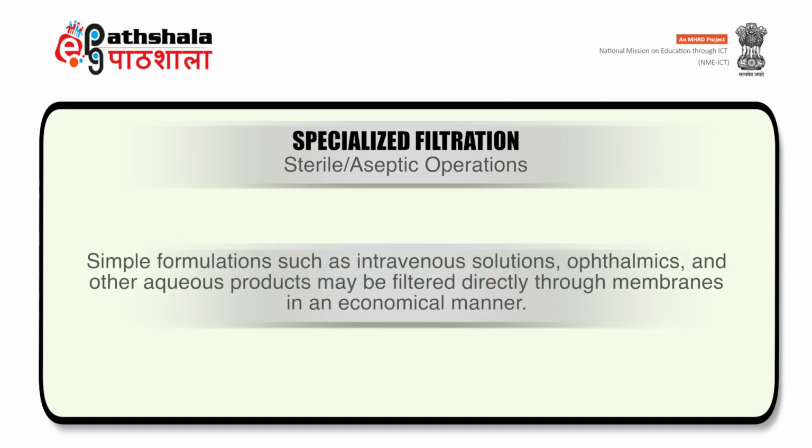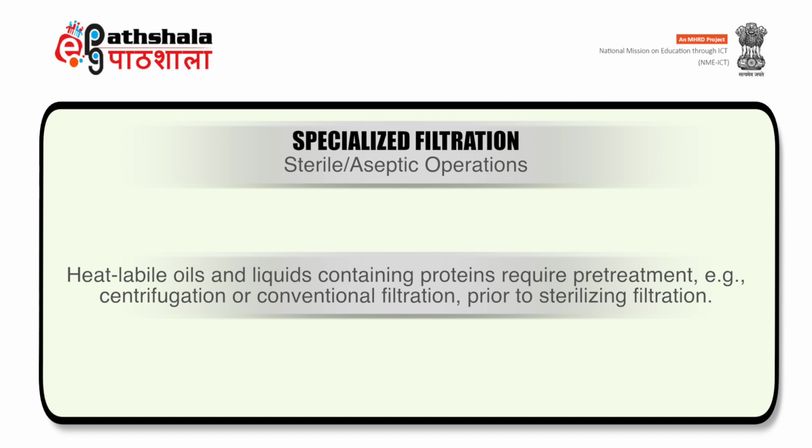For example, simple formulations such as intravenous solution, ophthalmics and other aqueous products may be filtered directly through these membrane filters. However, heat labile oils and liquids containing proteins require pre-treatment, for example centrifugation or conventional filtration prior to sterilizing filtration.